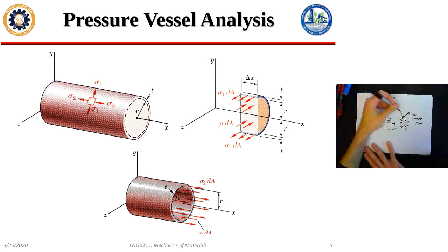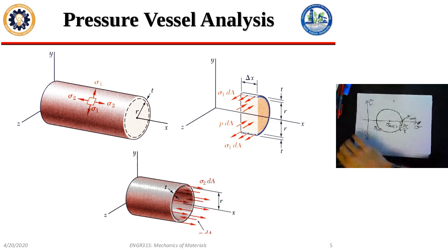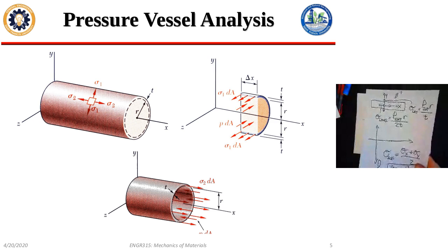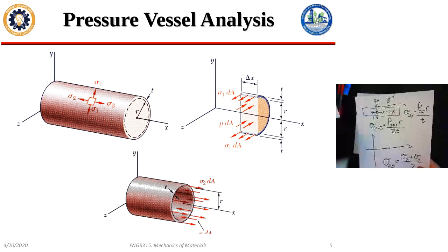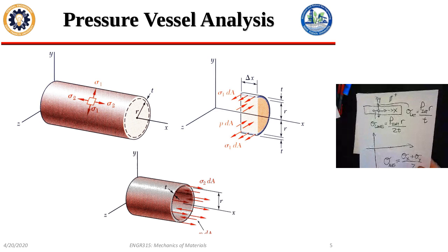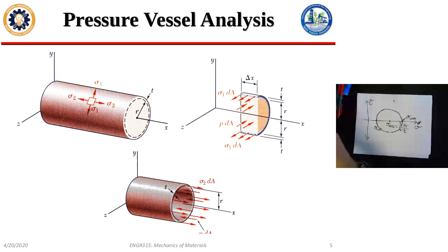Because I don't have any shear stress in how I solved it, I know that in Mohr's circle, in my original state of stress, the one that I've drawn here, I only have normal stress. So in Mohr's circle, I expect the computed stresses to end up on my sigma axis, or in other words, where shear stress is 0.